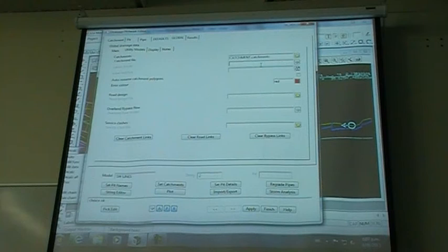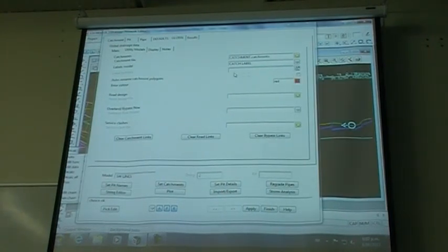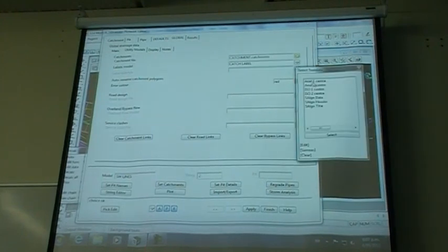The labels model, we're going to create a model called catch label, so that once it's run this, it's automatically going to label our catchments for us. And under our label text style, which is a little greyed out box here, I'll click on the more information button, and I'm just going to pick Arial 1 Center.